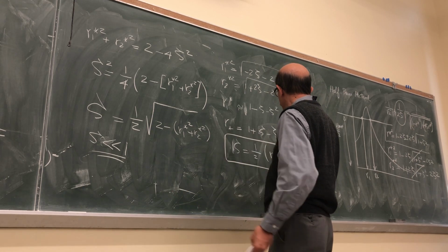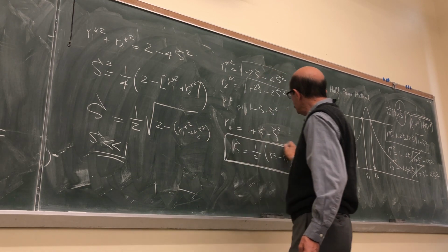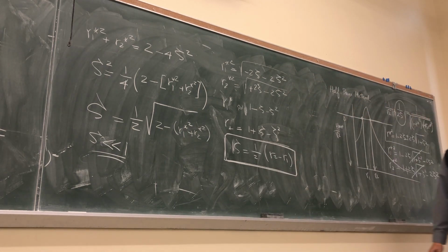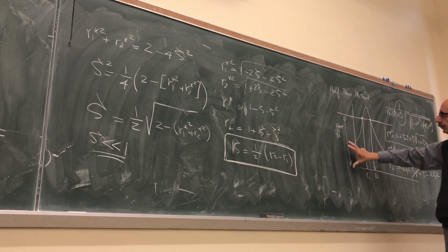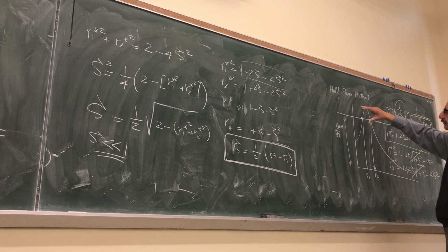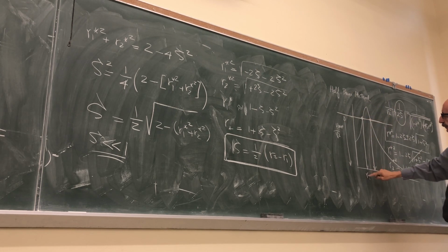This is the expression that is typically used to find the damping ratio. So what you basically do is roughly consider 1/√2 of this peak, approximately. You cut this curve, you find these two roots, you just measure those.